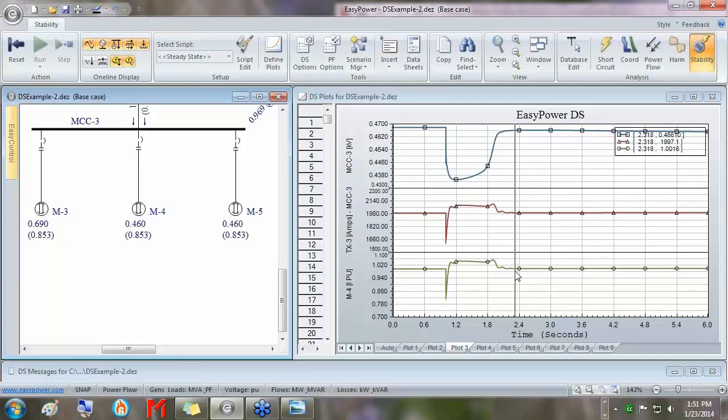If you're ever near the edge of a voltage collapse or something in your system, note, if you have voltage depressions like this, you can cause other things to draw more current and thus make it worse. Yeah, it'll just make the voltage depression worse because more current is now being drawn through, for instance, transformer 3 here that feeds MCC3.